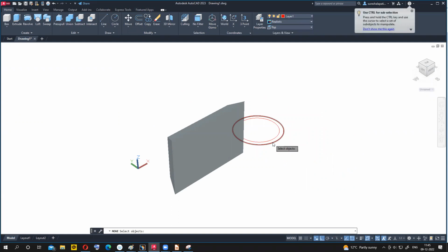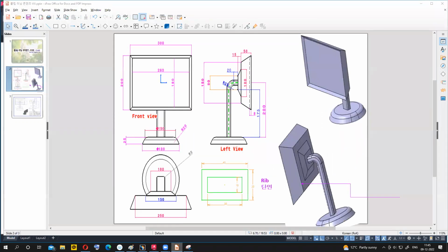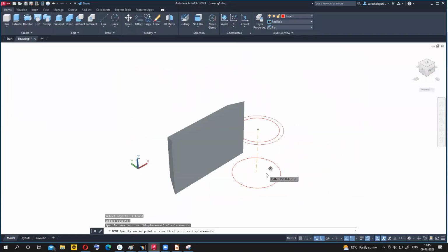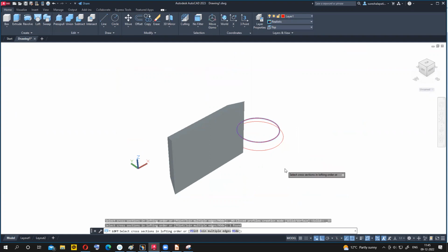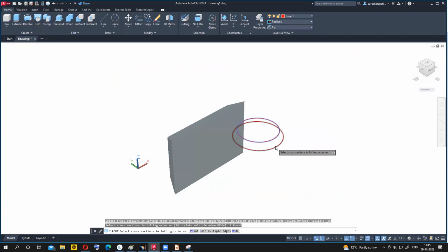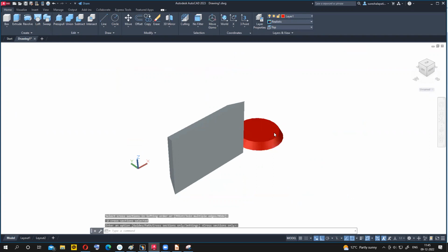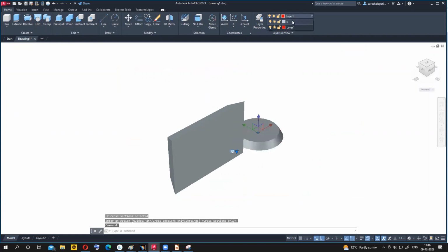So we should move the top circle, right? Move the top circle, enter, so turn on the auto. So from the center to, what is this one? The gap, 25, right? 25. And use the loft operator. So this circle and this circle, and change the color.